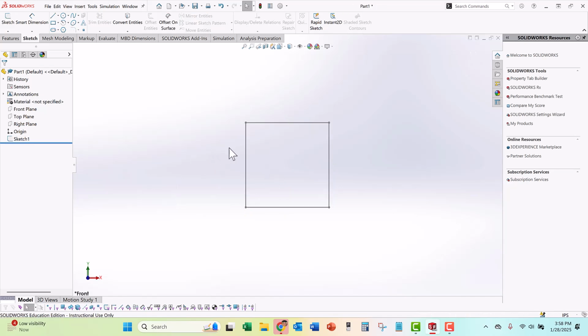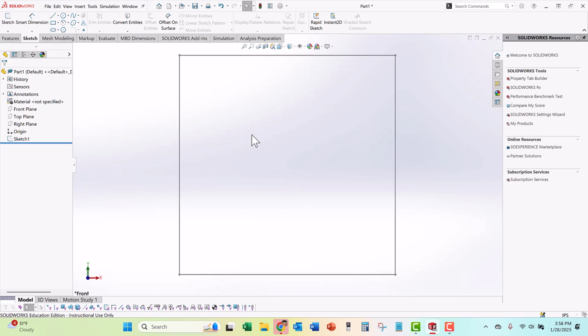While we're talking here, let me talk about how to manipulate your model. Definitely need to have a mouse with a zoom wheel. I roll my mouse wheel in and out to zoom in and out. Wherever my mouse is, when I roll the wheel, that's where it zooms. So if you want to zoom in to your sketch, if you have your mouse over here, it's going to zoom off the screen. If you lose it and you can't find where it's at, double click on the middle mouse wheel, and it'll pull it back full screen for you.